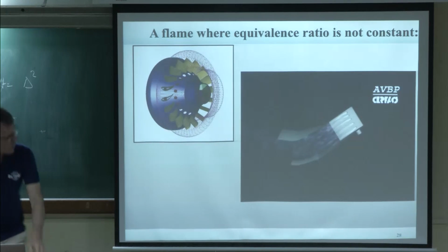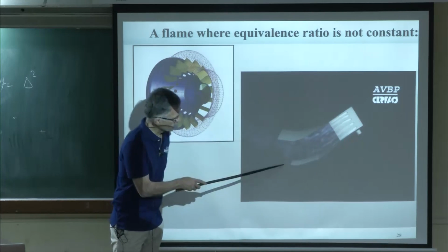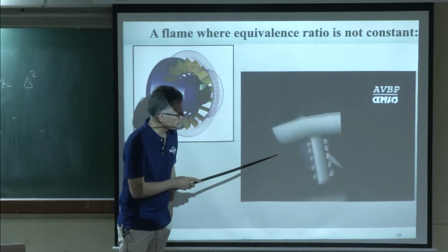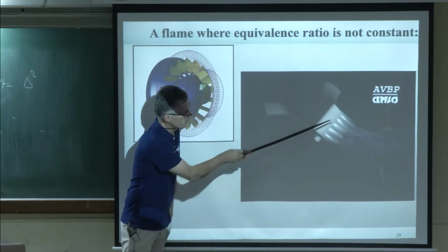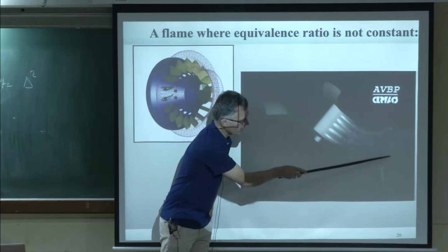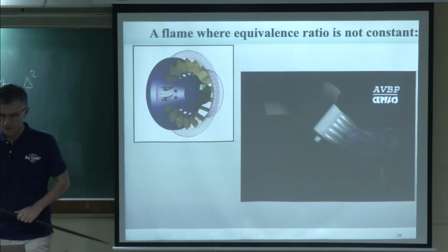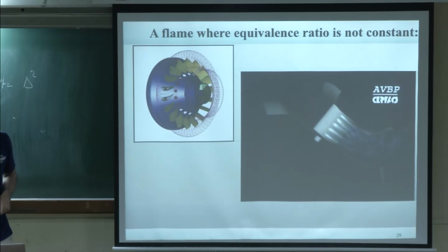That's a film which is just showing that the equivalence ratio in the chamber is not constant. You have mixing issues here. These jets merge, and when the premixed gases enter the chamber, they are not fully perfectly premixed, which means that will change the response of the flame.